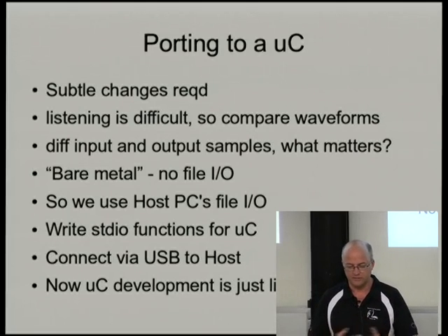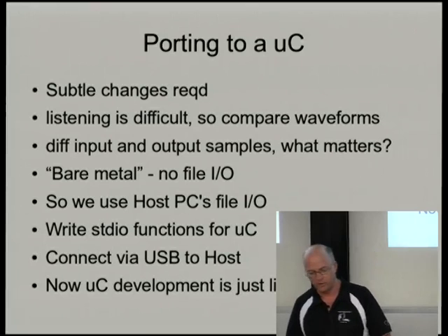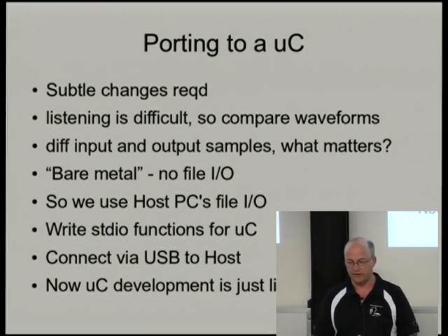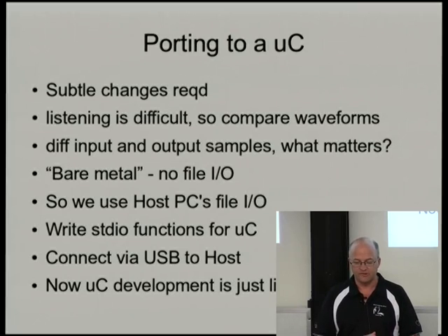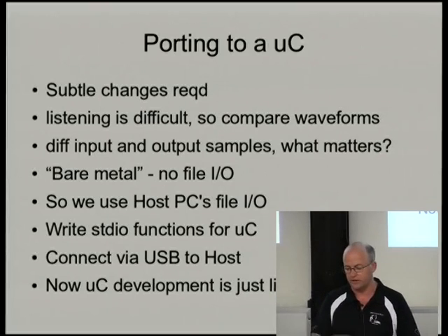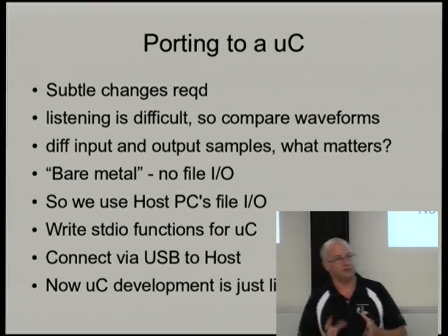Given I wrote the codec, that gives me a little bit of a head start, knowing what matters and what doesn't. The microcontroller has no operating system. It's bare metal, so it's just running the codec in a loop, or maybe in line with some other code like the radio code or the modem code. So that means it's got no file I/O. It does, however, have debug access via USB and via GDB support.